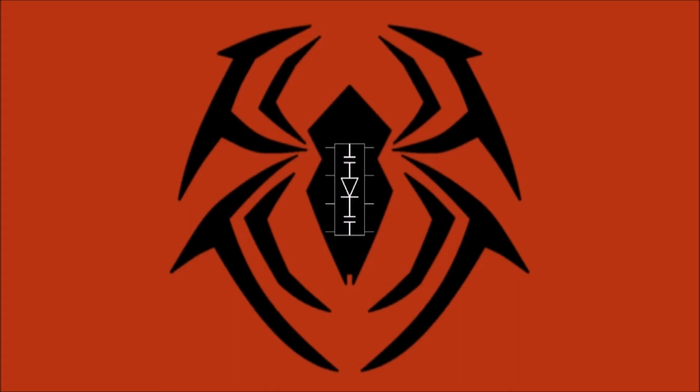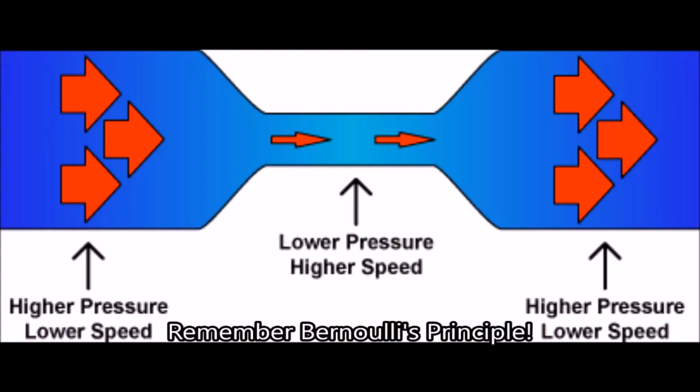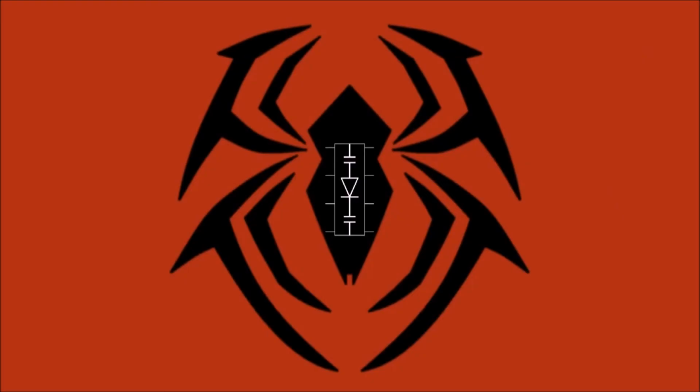Now, admittedly, the fluid is going to be moving at quite a high speed within this tubing most of the time, and it will be open to the outside through the eventual directing mechanism, so the pressure won't be nearly what it is inside the idle pressure vessel, but it will still be fairly high, all things considered. Even if you're using some kind of heating coil and have copper or some other metal tubing, there are instances where even that may be too thin and can burst. Make sure you reinforce any tubing you use just as well as you reinforce the pressure vessel itself.